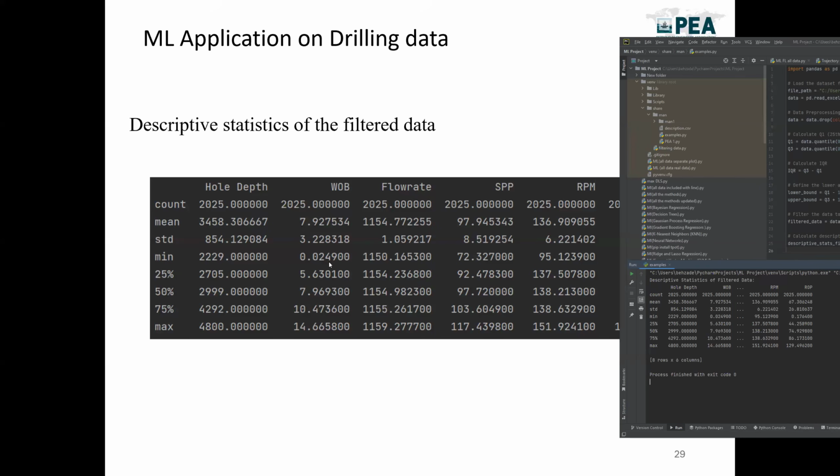So by this method, you can start getting rid of the data which are outside of the lower and upper bound, which will help you to get rid of all those data that I mentioned at the beginning. As an example, if you have the RPM data, which should be around 120, 140, but when you plot them, you see that you have one or two data points showing you 1,500, which normally we don't have as an RPM.